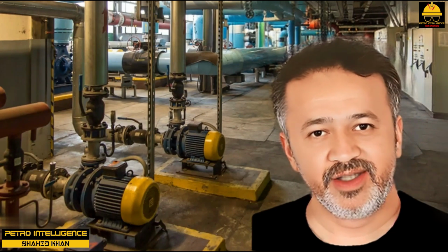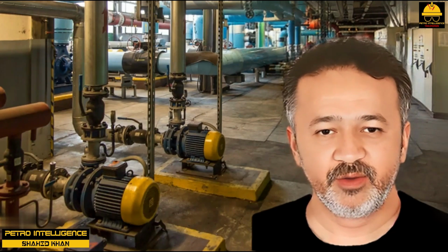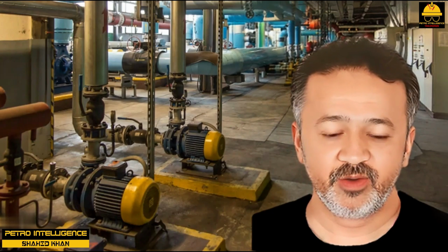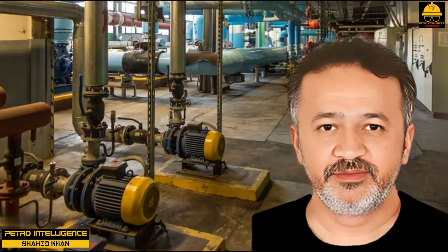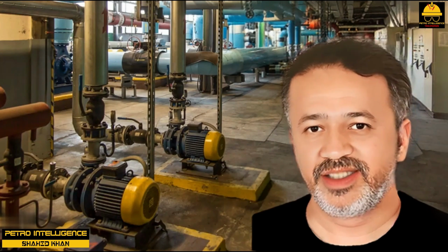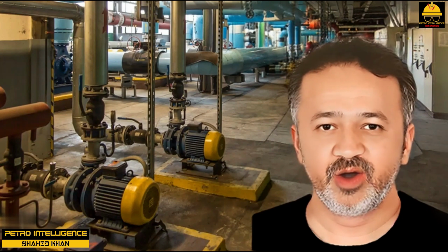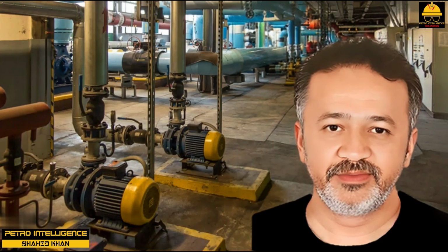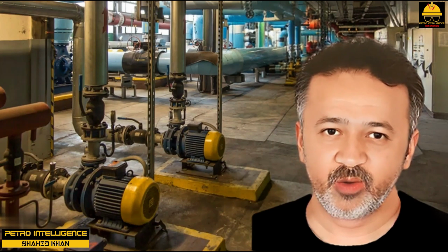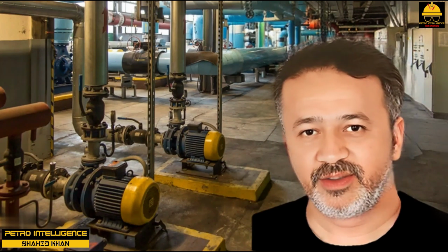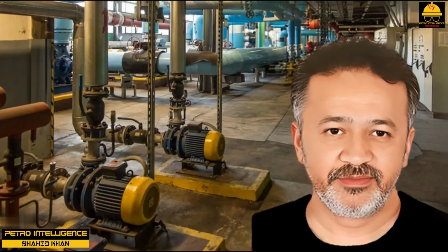A typical, but not general, program for motor bearing lubrication is 3 or 4 squirts from a grease gun every 6 months. There is a device now available on the market called a bearing buddy, which delivers a consistent grease supply pressure over an extended period of time. Motor bearing failures at one process facility disappeared when these bearing buddies were installed.